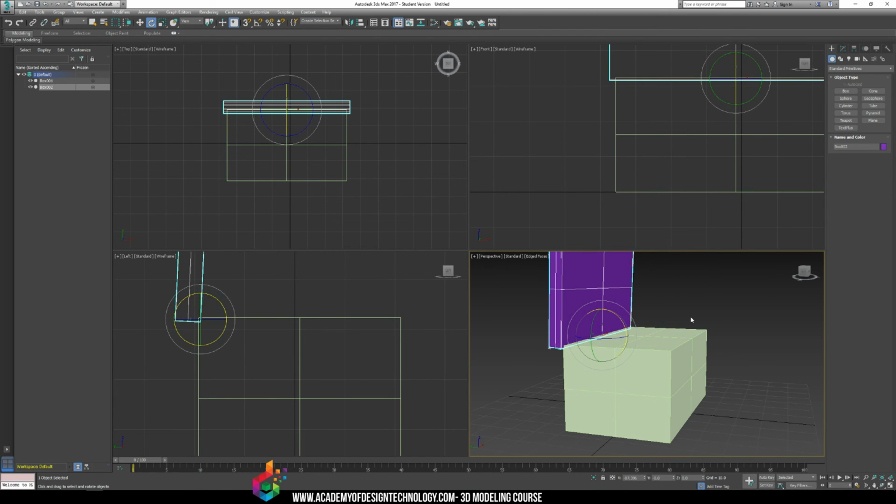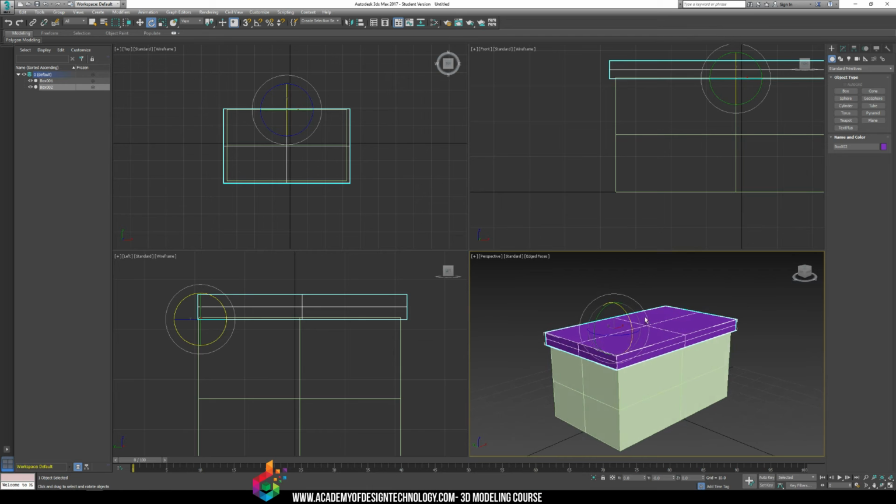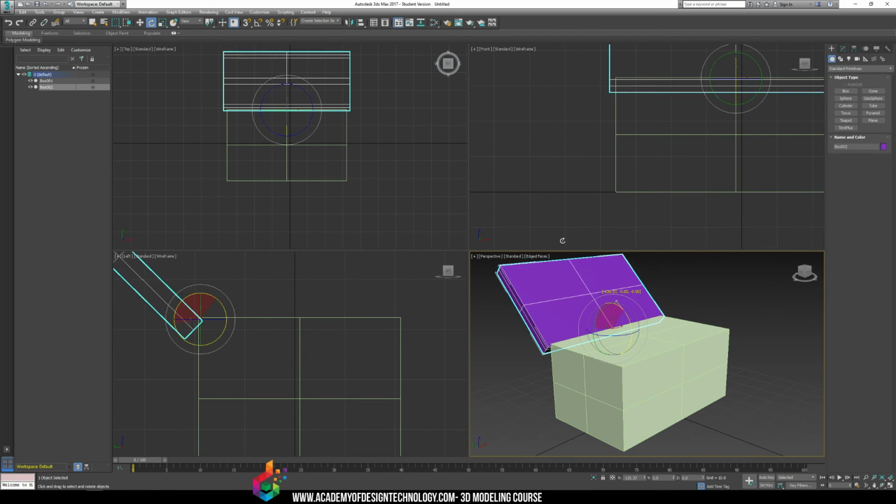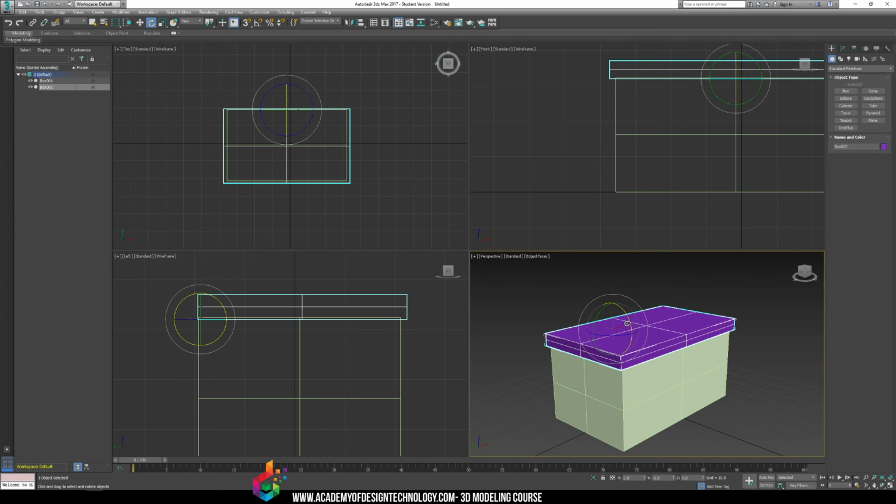This is an easy way to create simple animations or simple objects inside 3D Studio Max that can be used and animated properly without having to do any rigging at all. By adjusting the pivot points in the right location, you're able to move and manipulate objects much easier. So don't forget, that's in the third panel at the very top. That's our adjust pivot panel, and we can affect pivot only. When the big arrows are on, that means affect pivot only is on. You can always turn them off just by clicking that.